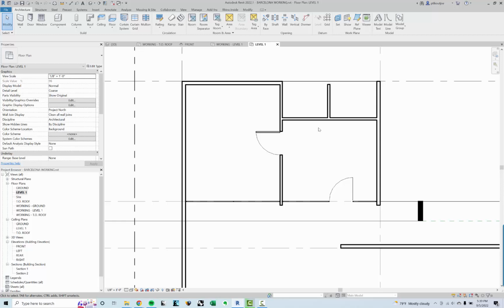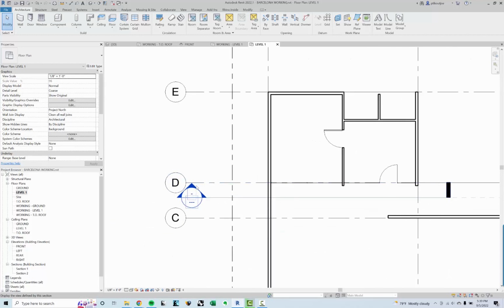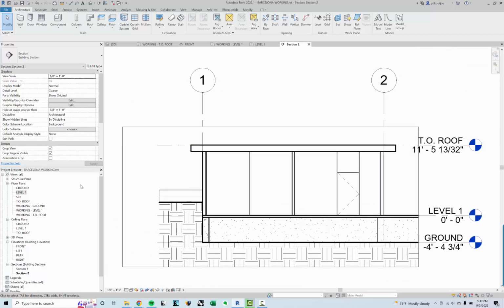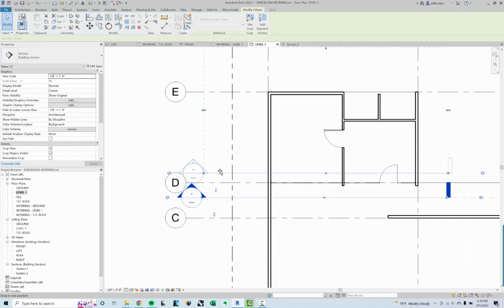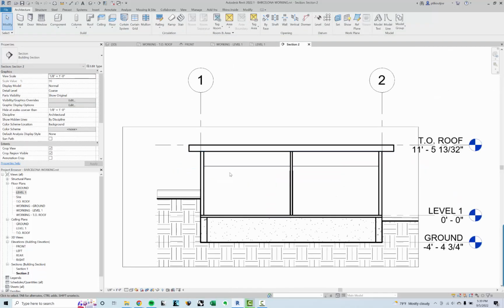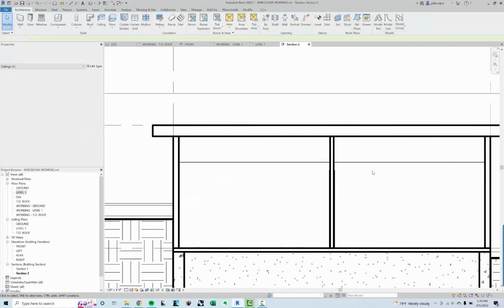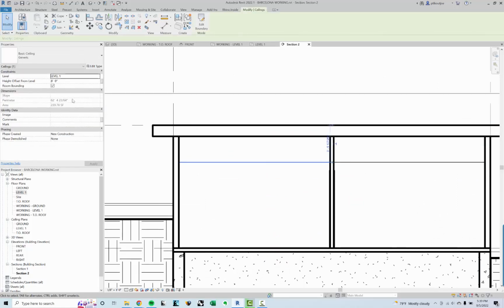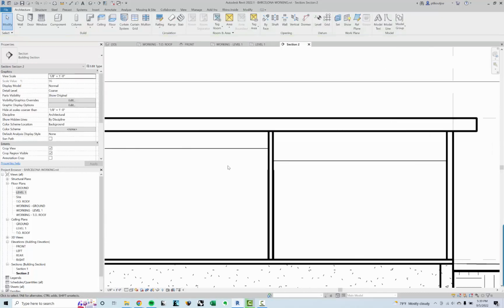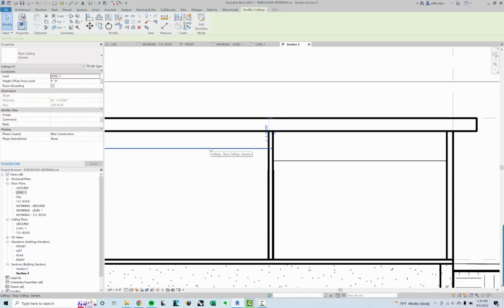Or you might have exposed ceilings, right? You might have a steel frame with fireproofing or painted underside with exposed ceilings, or a concrete slab or something like that. And then you have to figure out a different way to get your lights hosted. But again, the ceilings are pretty valuable for that. What I'll show you is if I look here, I can't see those things. But I might just take this section and slide it up just for the sake of being able to illustrate it. So there's my ceiling. It's 8 feet from the ground. And I can change the offset of the level there, and it will adjust. So ceilings, very straightforward, very easy, and so on.